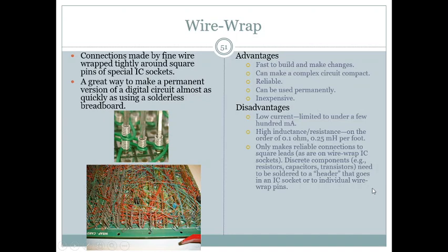Then you have this wire wrap. People have been using this as a permanent technique, right? You put all the current components into some support like a wooden board, and you make all the connections by wrapping a wire and connecting the other end to the other component. Which is beneficial because you can make the circuit without much delay, and large currents can be drawn, but the drawbacks are that diagnosing is not that easy.